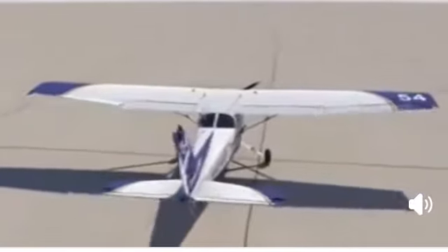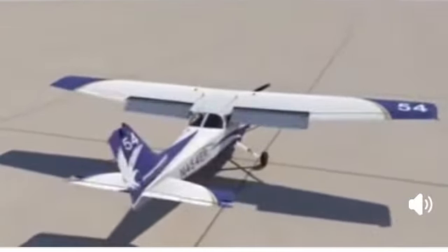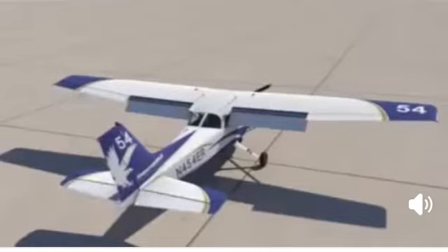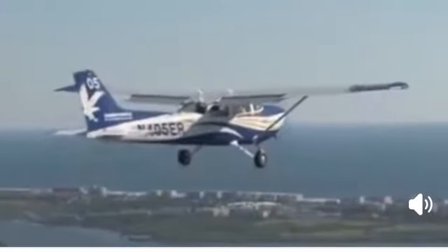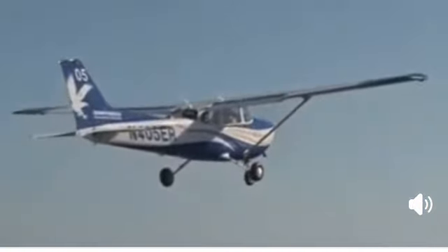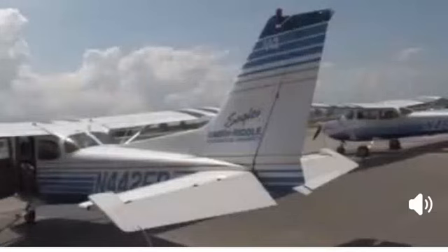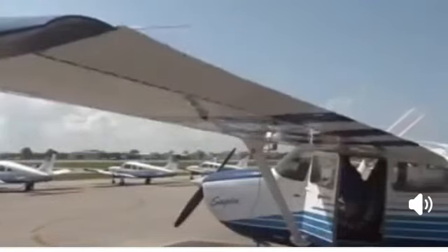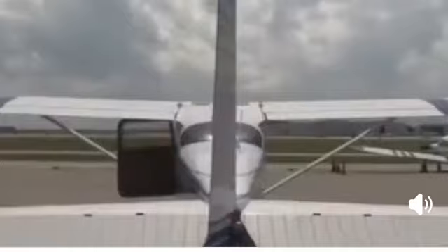forces on the plane, allowing the pilot to control the aircraft. Aircraft flight controls are broken into two systems: primary and secondary flight controls. Primary flight controls are simply those flight controls that the pilot primarily uses to control the airplane. The three primary flight controls are the ailerons, elevator, and rudder.